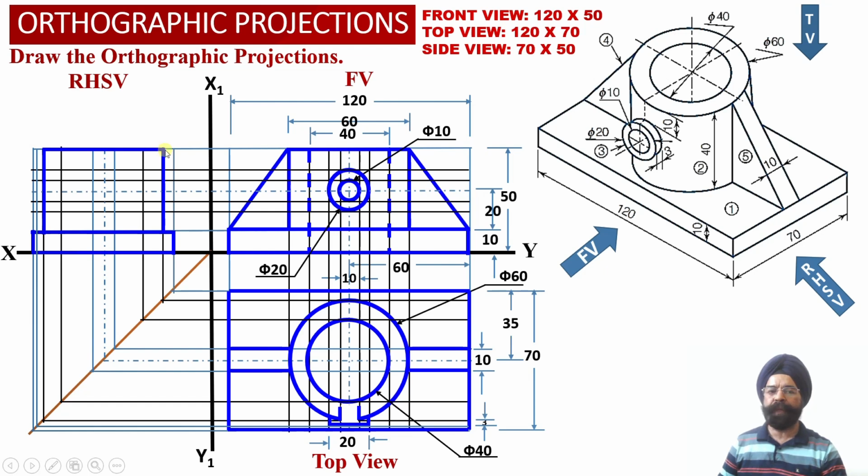We are going to obtain apparent shape rectangular projections corresponding to the cylindrical outer surface of this hollow vertical cylinder in the right hand side view projections over here. From the right hand side view, the internal diameter of 40 millimeter will not be visible to the observer, so we are going to obtain the dotted line projections over here in the right hand side view projection.